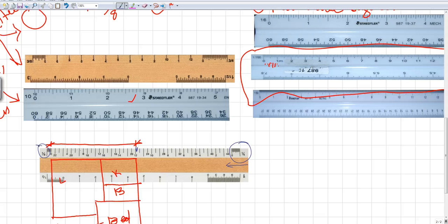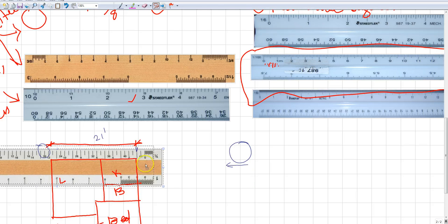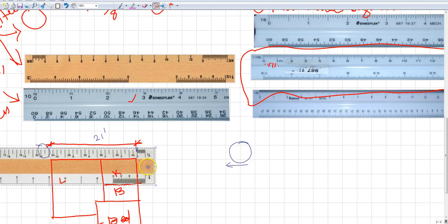So the dimension that I have in my drawing right now is 21 feet, right? So that distance I measured with an architect scale of 1/8 gives me a dimension of 21 feet. Now if I were to use 1/4 scale for the same exact thing, I'm just going to move it till it lines up. It lines up right there, right?